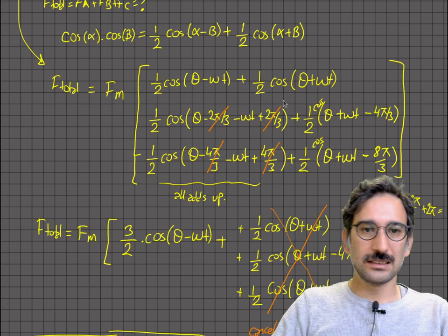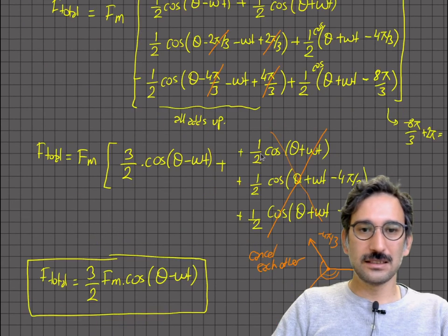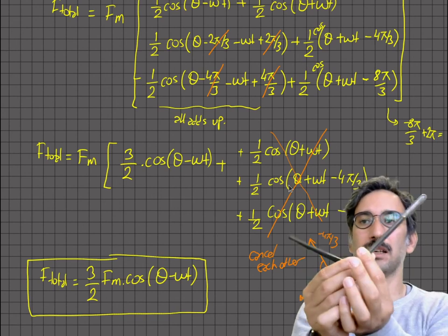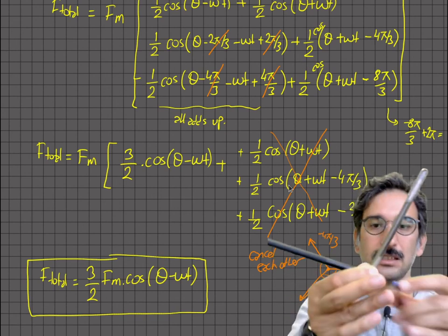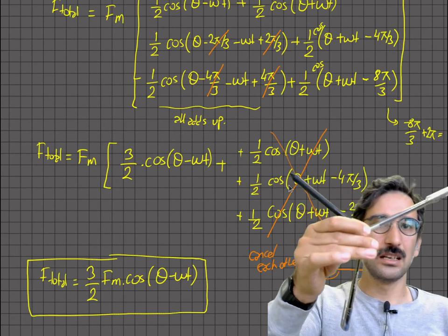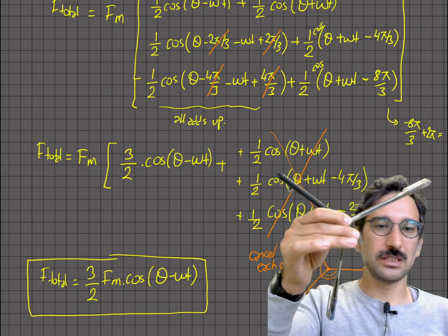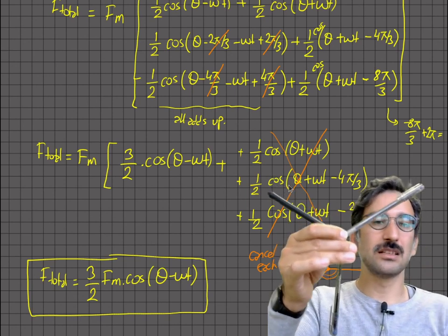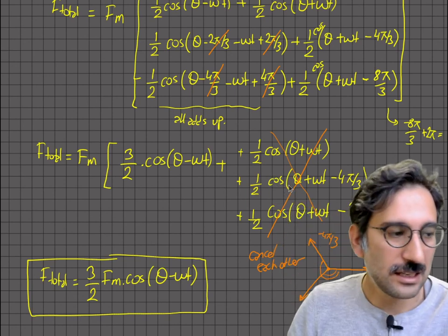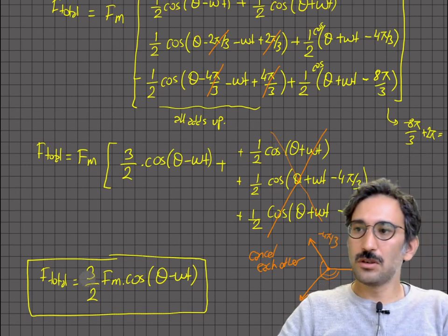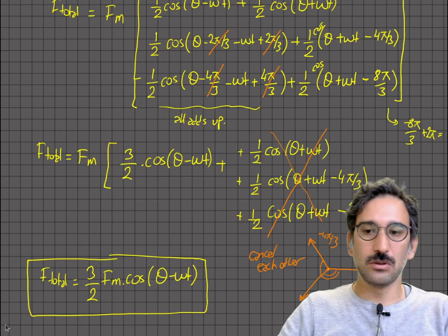And then the second ones, they have the same magnitudes, but they are all separated by 120 degrees. So they are like phasors, like vectors, each having the same magnitude but a different direction. So if you add all those 3 vectors, they cancel each other, and you get 0 from the second term, and that is what you obtain.